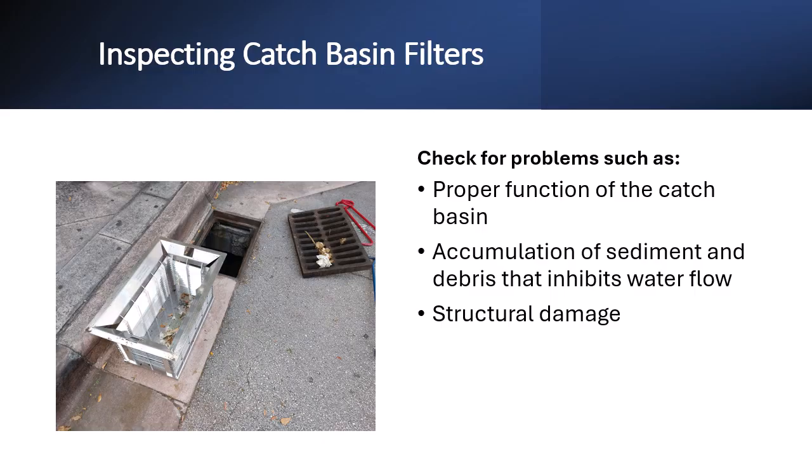Inspection of a catch basin filter starts with the catch basin itself, since damage or problems with the catch basin could cause the filter to be ill-fitting or otherwise inhibit its function. Then check for accumulation of sediment and debris in the filter, particularly if it's inhibiting water flow through the filter. Some filters may need more frequent cleaning than others. Also check for any structural damage to the filter itself and replace as needed.